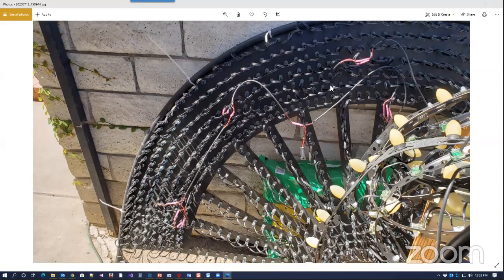If it's full white, everything needs it. But if I'm running a full white sweep, the power draw is going to shift all the way through the prop. And by doing it this way, the power shifts with it and gives those pixels the maximum amount that they need. You don't always have to; there's no hard and fast rule on where power injection needs to go.